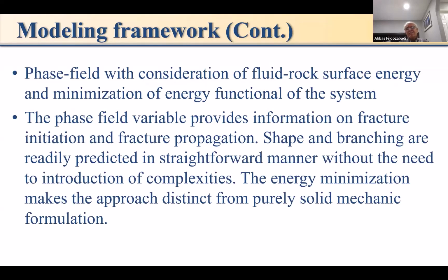The second approach is the phase field. Part of it is that we have to include the surface energy and minimization of energy, like a lot of other problems we have. So we should get everything we want from it if we can do it properly. It provides information on fracture initiation and fracture propagation. Shape and branching are readily predicted without adjusting parameters. I think it's very different from purely solid mechanics or the conventional approach.